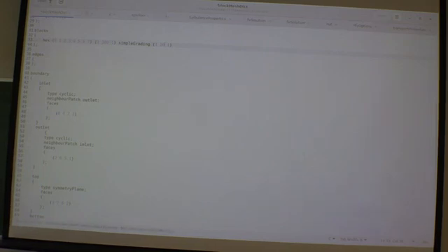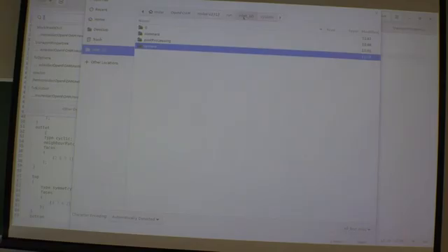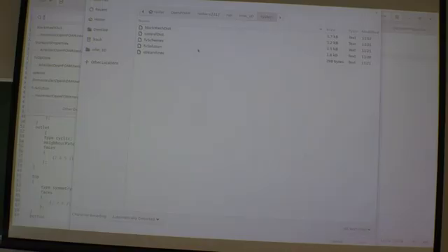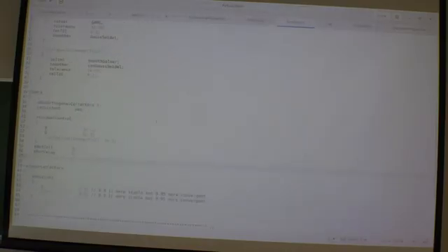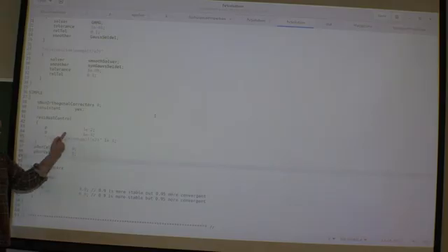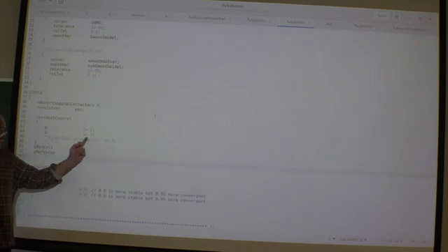And then finally, since it refused to give me a solution that is converged, here is a little trick. Here you have a residual control. So the pressure and the velocities are given with some numbers, and then for all the other equations as well.